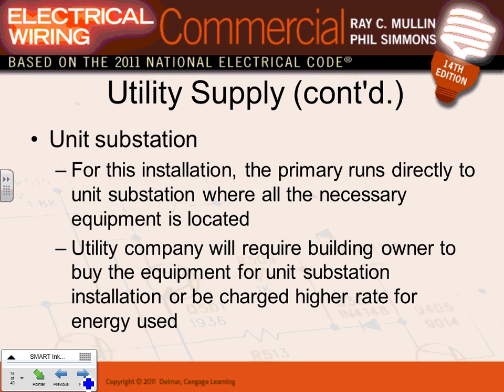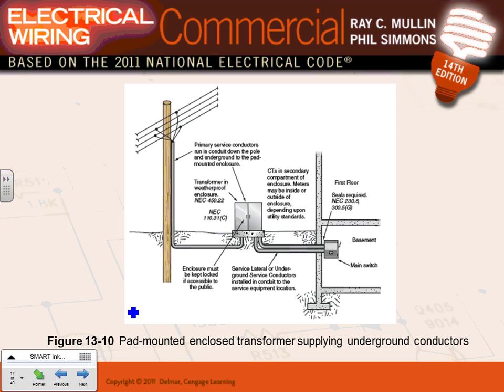So, cool, good one. We talked about unit substation, guys. That's the one where they bus all together, put the transformer, the high voltage, the transformer, and low voltage together in the same box. It requires the owner to buy the equipment and maintain and troubleshoot it. So they have to have experience in the high voltage section.